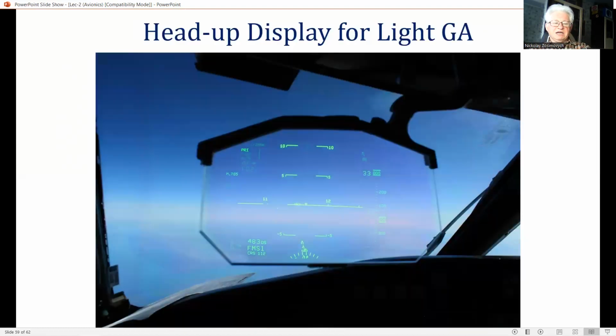Blind landing guidance can be derived from the ILS system and enhanced by mixing positional information derived from the global positioning system data using appropriate algorithms. This guidance information can be drawn cursively on the HUD together with primary flight information using suitable symbology. Such a system is known as synthetic vision, as distinct from enhanced vision. The latter system uses radar or infrared scanning systems, as described, and the imagery is raster drawn with stroke-written symbology overlay.